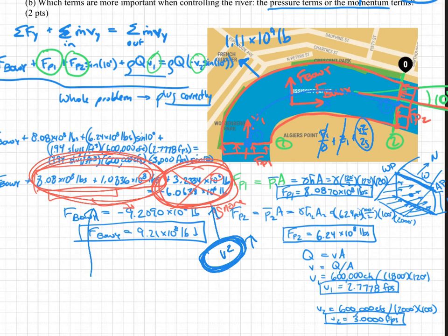Well, it works because there's all kinds of forces between 1 and 2. So you can't say that this is inviscid. There are forces acting on this thing between 1 and 2. There's a lot of viscosity going on here. There's normal forces on the sides. Even if these were the same, this equation would yield you nothing. It would just be a bunch of zeros, and you'd be like, okay, well, it's not helpful. So what if I go at depth? If you go down, let's suppose, 50 feet, now they've got hydrostatic pressure, so the pressures are the same on both sides. The Zs are the same, and you end up with the same problem. So Bernoulli is just really not helpful here.